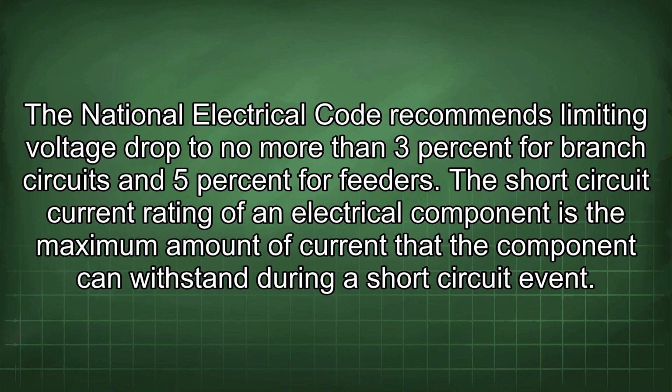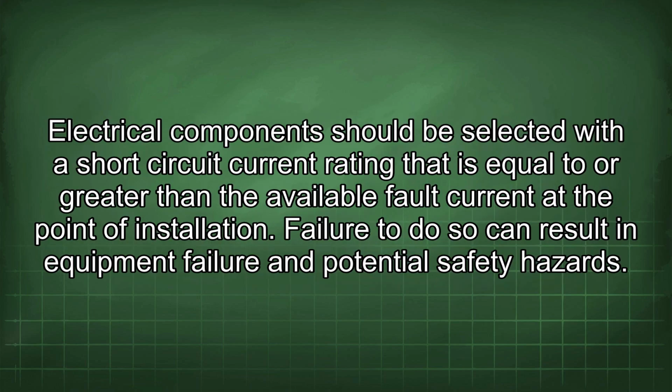The short-circuit current rating of an electrical component is the maximum amount of current that the component can withstand during a short-circuit event. Electrical components should be selected with a short-circuit current rating that is equal to or greater than the available fault current at the point of installation. Failure to do so can result in equipment failure and potential safety hazards.